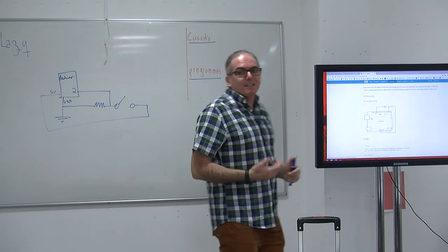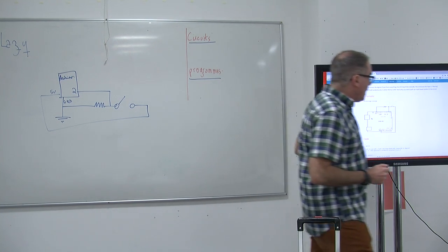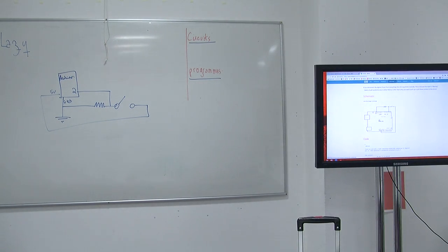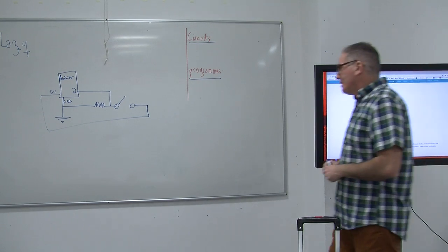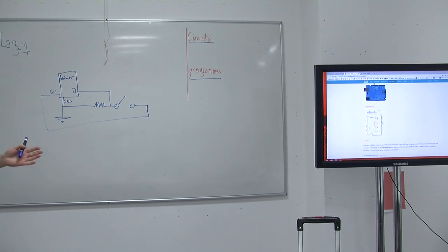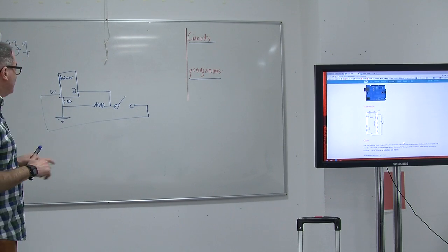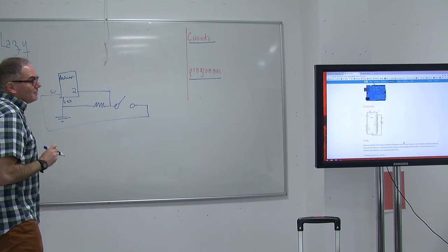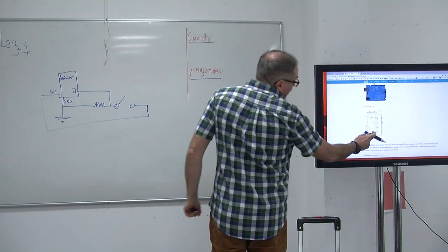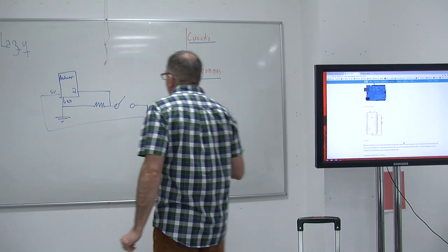we want the circuit for the LEDs, which is the one for the blink. So, we go to the blink example, and we can see that the circuit is like this. So, what are we standing on? So we all share the ground, okay? Your ground is always shared. That's one of the golden rules of electronics. So we share our ground, and then out of the ground there's a connection to the LED, and then to a resistor, and then it goes to pin number 13.